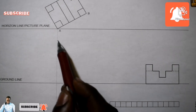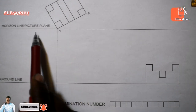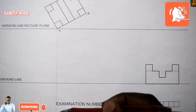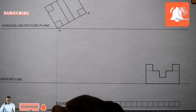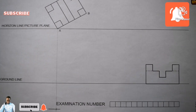You understand? And you have your CV there, but in this case they are saying the horizontal line is in the same line as the picture plane. So we are going to use it exactly the way we are given. From there going down is my 100 millimeter. So I get the 100 millimeter right here. Where this vertical line and this one are perpendicular to each other, I am going to say this is my SP, which stands for stationary point.